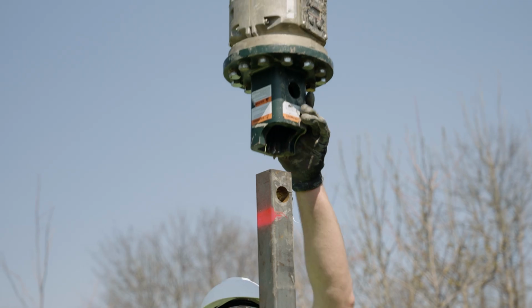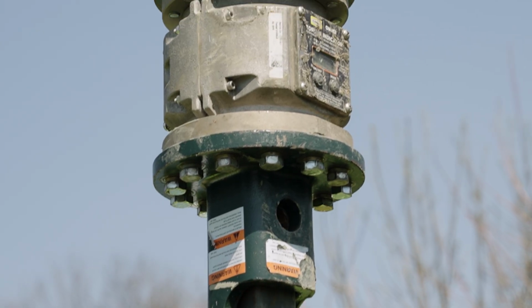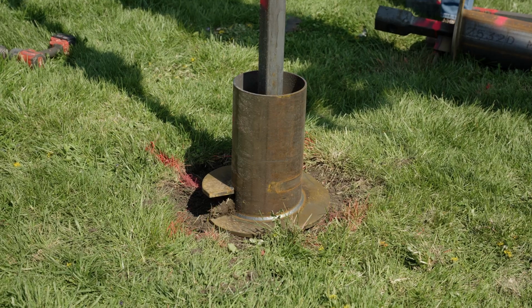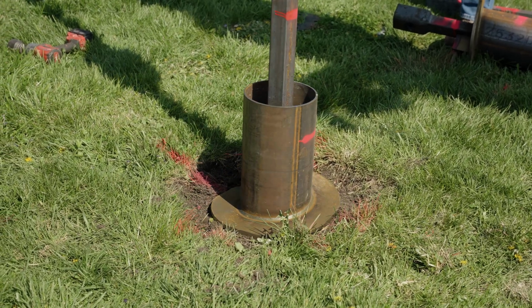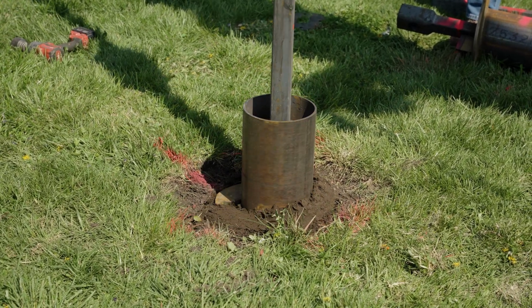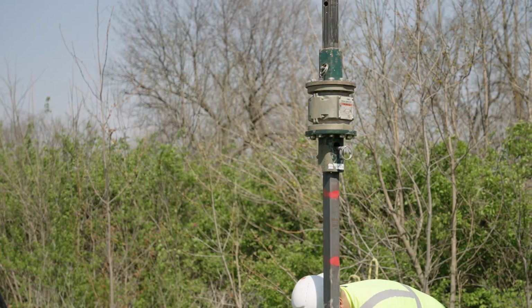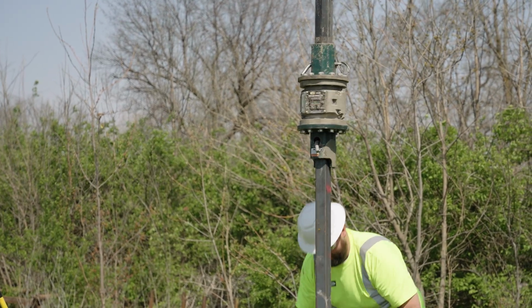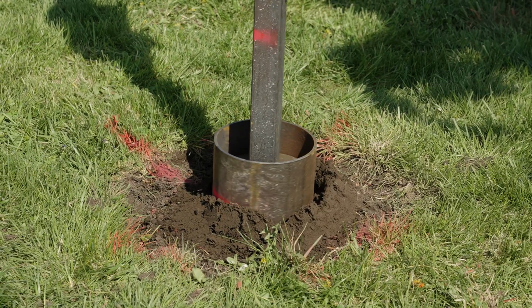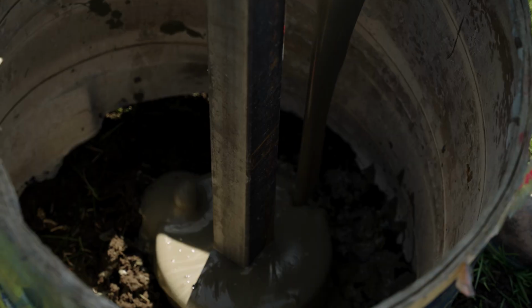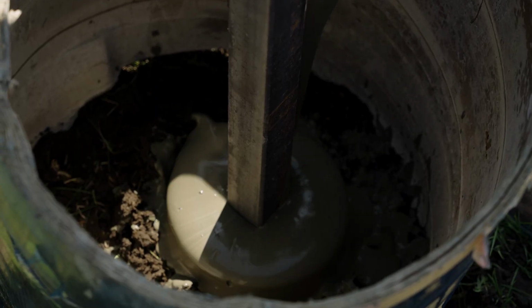After the GroutForce lead section is connected to the tooling string, engage and advance the pile into the soil in a smooth, continuous manner at a rate of 8 to 20 rotations per minute. Apply sufficient down pressure to uniformly advance the GDP sections at 80% to 100% of the helix pitch per revolution. Place the grout in the reservoir prior to advancement of the lead section into the soil.